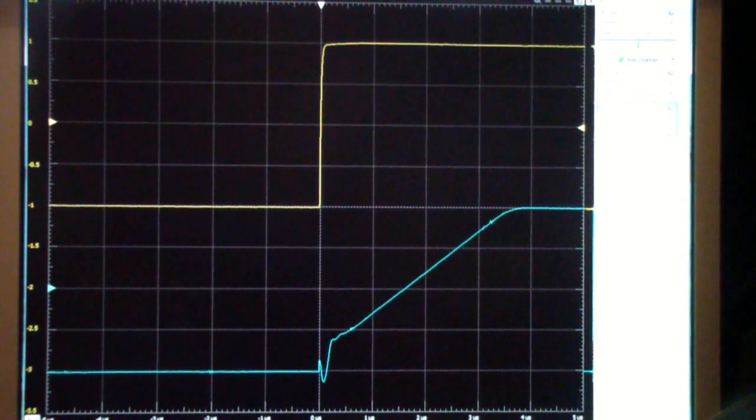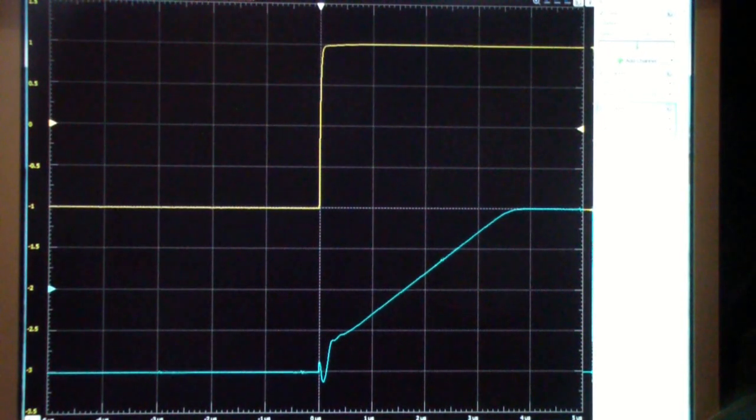And the reason slew rate is important is you can't just look at the frequency response. Instead, you also have to look at the slew rate, particularly if you are swinging the output voltage quite a ways. Now what I'm going to do, before I show you the breadboard itself, is lower the power supply voltages.